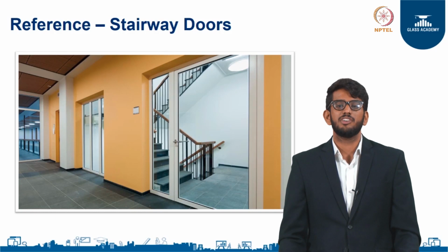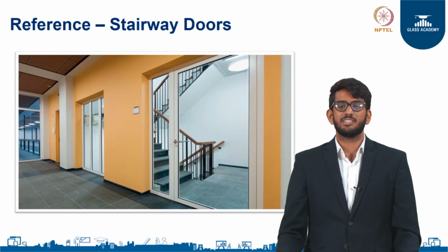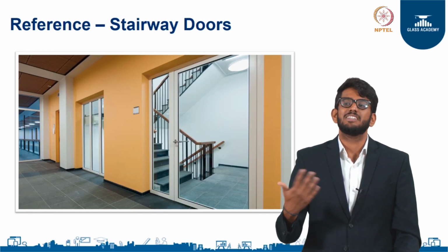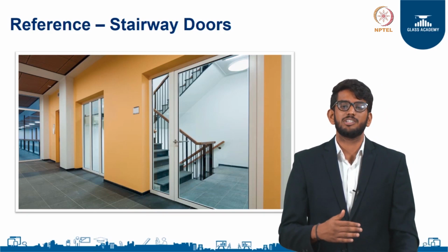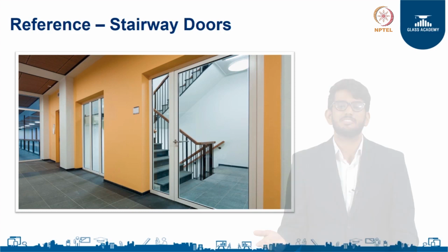Again, if we do not use a fire resistant system in this place, there is a possibility that the fire could spread from the area of occupancy into the fire exit passage. So, when people are being evacuated through these areas, if there was a fire spread into this area of evacuation, then it hinders the whole evacuation process.